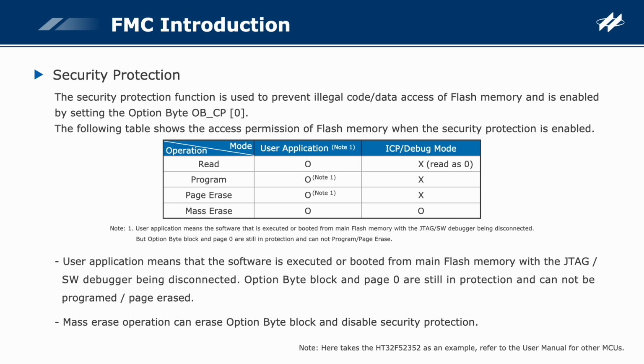But the option byte block and page 0 are still in protection and cannot be programmed or page erased. Mass erase operation can erase option byte block and disable security protection.